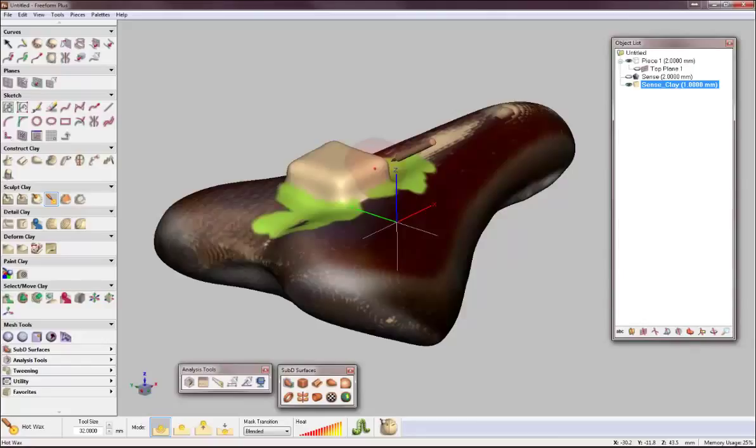And when we say organic shapes, you're talking about people, dinosaurs, very intricate, complex shapes that otherwise would be very difficult to do inside of CAD. So its approach is to extend CAD in that direction, where it's Freeform shape modeling, but yet circle back around and dump its data back inside of CAD for manufacturing. The Design X product is going to take scan data from real-life objects, help you design more prismatic shapes, but not always, and dump that inside of CAD as well. So that would give you an idea of the two different markets that they're designed to address.